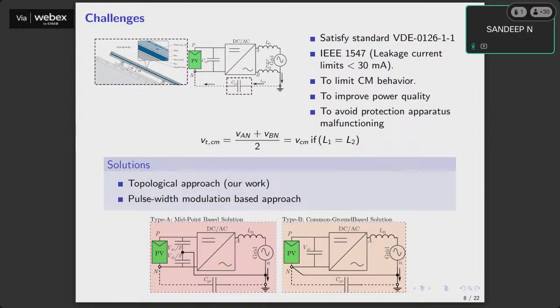So that is the reason we have to split the inductor into two. Whatever the design you are going to make, for example, if the design says you have to go with a 3 millihenry inductor, then we are going to split 1.5 and 1.5. So this way, in both the paths, we are going to attenuate the common mode current. So that is the reason we have two inductors over there, which is to take care of the common mode current.